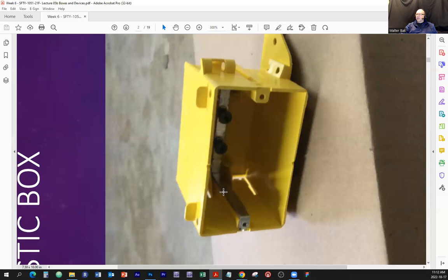So it is basically brought out right to one of the screw terminals. So then the chassis of the switch, and we will look at the pictures a few slides down the road, is touching this bonding terminal, which means it is bonded. Or if you have the bonding screw terminal, you can still put that against it. So it's either or, as long as it's bonded.